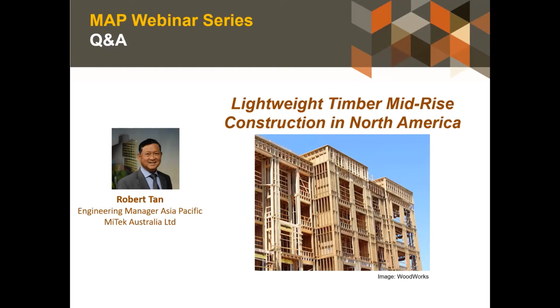during construction stages, the nogs would certainly help to provide the lateral stability. But once you fix the OSB and other linings on, the reliance upon the nogging is almost non-existent. It is no longer really a big issue. It is only during construction loads. When you talk about loads, the construction period is usually only a matter of a few months, say 5 months. So your duration of load factor is somewhere in the order of 0.9. So it's quite high. In other words, you don't have to be overly sensitive about buckling when the loads are only for a few month period. It's only a long-term duration that you're more concerned about, and by that time, you will have your full lining on.